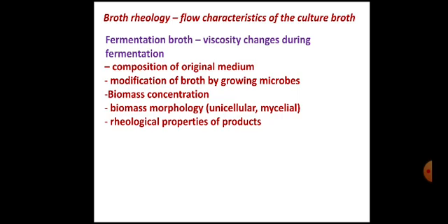So in those conditions, proper mixing and aeration conditions are going to be more focused, because if the broth viscosity increases, the solubility or volumetric airflow rate is going to be decreased, and therefore KLA is going to be affected due to this mycelial growth.